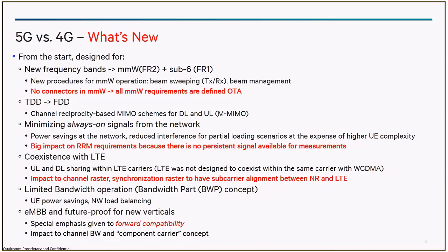So it's mandatory to support the 400 megahertz band. You support a particular band, the band could be as wide as 400 megahertz, and the network could actually keep you in a BWP of only 100 megahertz. So there is a BWP that you can signal that I support. For each individual UE, this is the maximum allowed bandwidth that I can support.